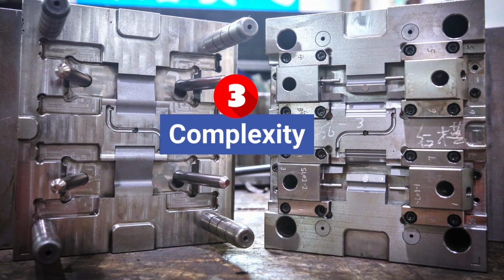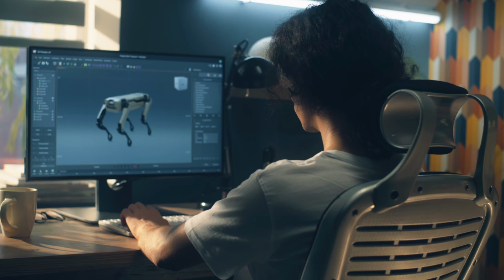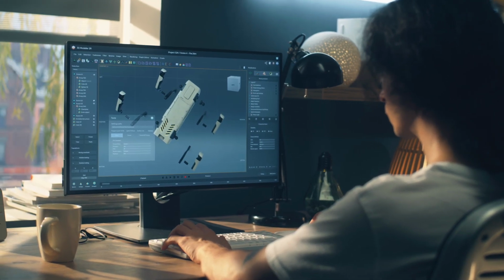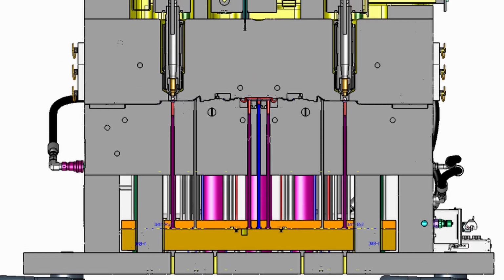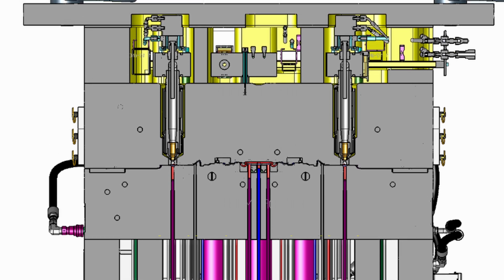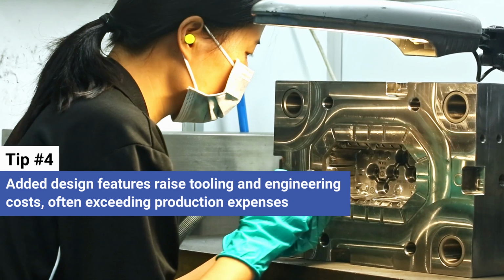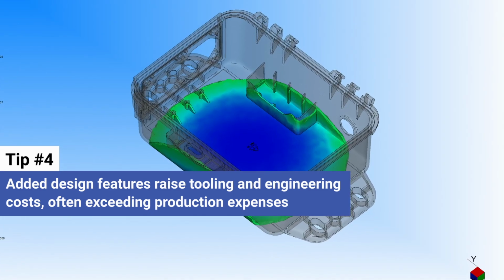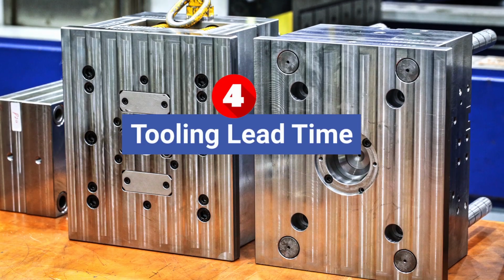Number three, complexity. Complex tools require more expensive engineering and fabrication, and this is where the product designer can most directly influence the tool cost by keeping the design as simple as possible. Every additional design feature represents more fabrication costs, not only in the cavity but also for the runners and cooling channels and other accessories. This also includes tool treatments such as polishing or photo etching. Also, remember that engineering time, representing design and computer modeling, is more expensive than production time. Number four, tooling lead time.